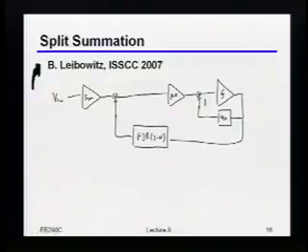So what is that label? Say that again? The labeling. The label. Oh, here. I just said it's 2 through n, meaning that it's taps 2 through n rather than the very first tap. All right. So in other words, there's at least one delay in this FIR filter here before you correct all of the residual ISI. Okay.